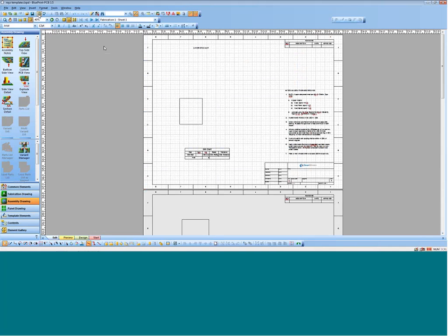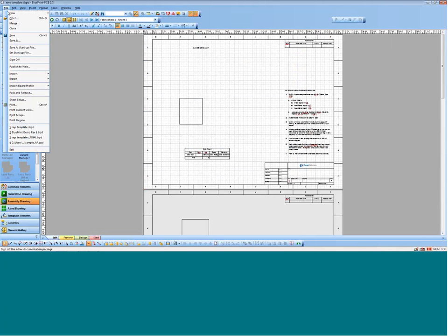So now what do I do? I import the CAD data. Currently we support ODB++ from most of the CAD systems out there. The exception being PADS, where we take the ASCII. The reason for that was their ODB was not ready when we created BluePrint. I believe either this rev or the next rev, there'll be a PADS ODB++ option.